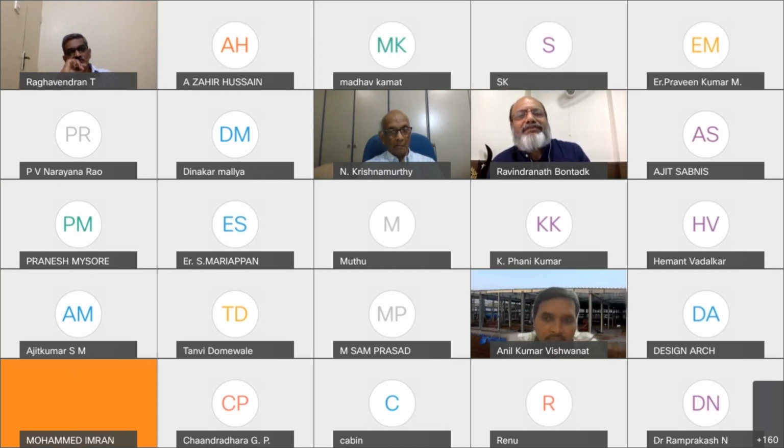Yes, I agree. But my take is that presently we are not using most of the sections in SP6. And one more thing, there will be equivalent sections we can show in SP6 which are useful for the present IS 800 code.